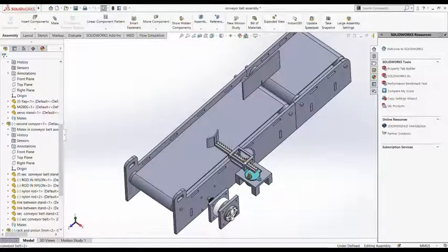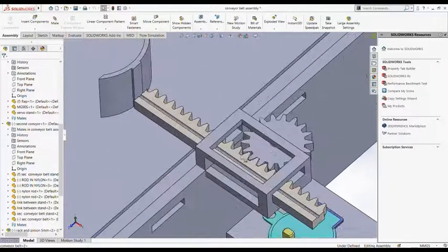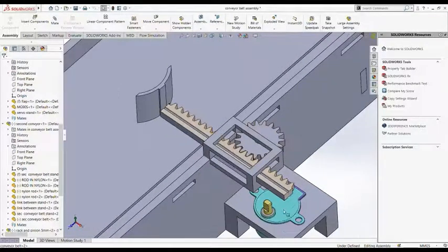The primary goal of this project is to measure the diameter of the bottle accurately. This system uses an arm to measure. The arm is movable, synchronized, and calibrated to a potentiometer. The arm is connected to a rack and pinion, which converts the rotary motion of the Arduino controlled stepper motor to linear motion.